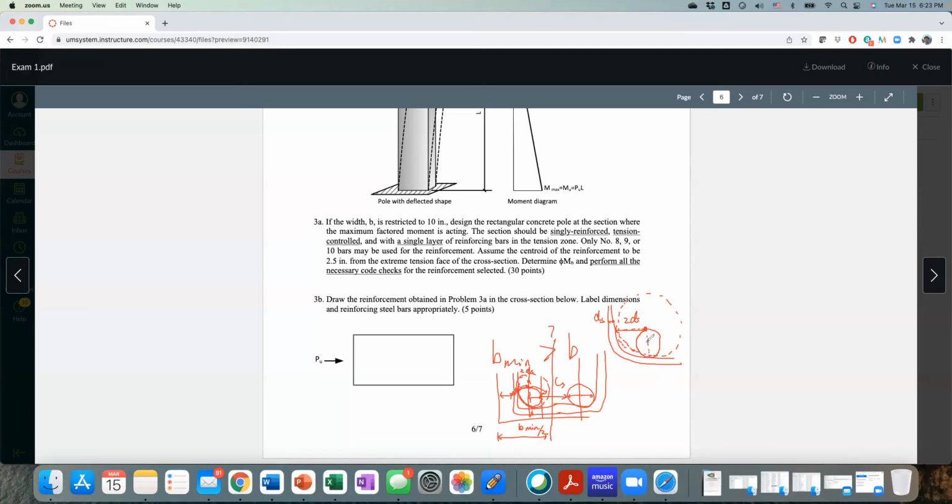Because we often align the bending center with the center of the bar. So they're level all the way across. That's why this distance from the inside wall of the stirrups to the center of the bar is 2ds.